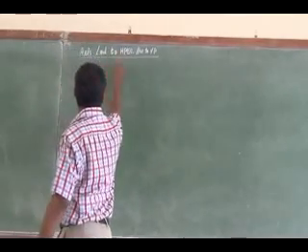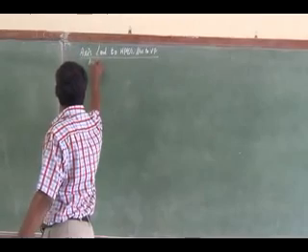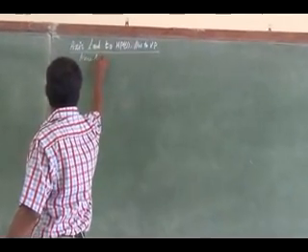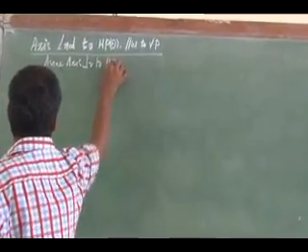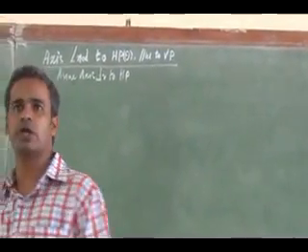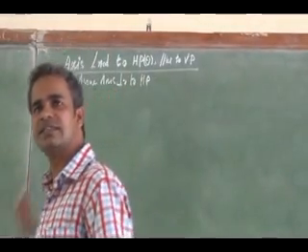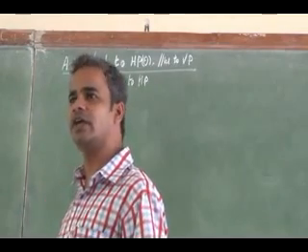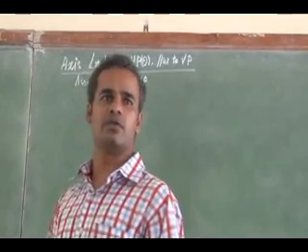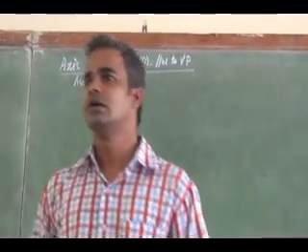So in two steps we will be solving this kind of problem, right? Here you see the axis is inclined to HP. So what I have to do is first of all assume the axis is perpendicular to HP, then I can draw the base. Since the axis is perpendicular to HP, the true shape of the base is obtained on the HP, that is in the top view, right? I can draw the true shape and proceed for the front view.